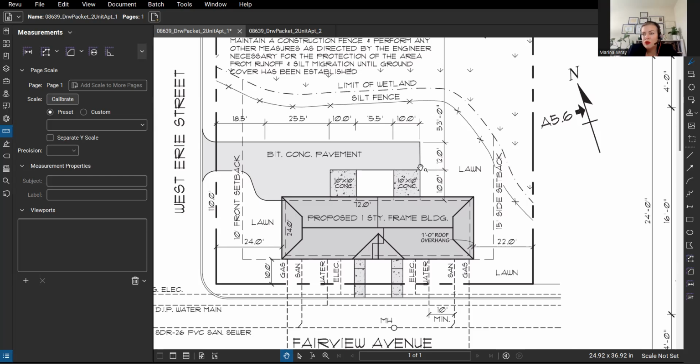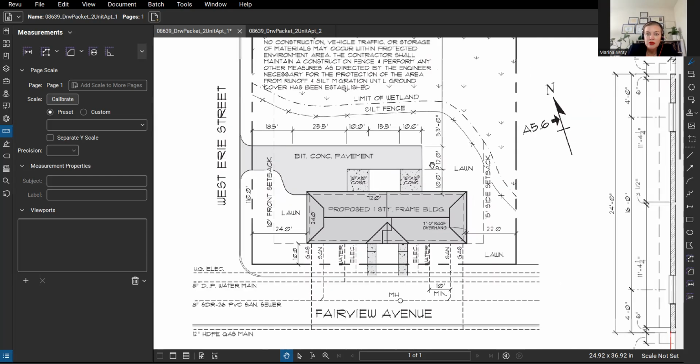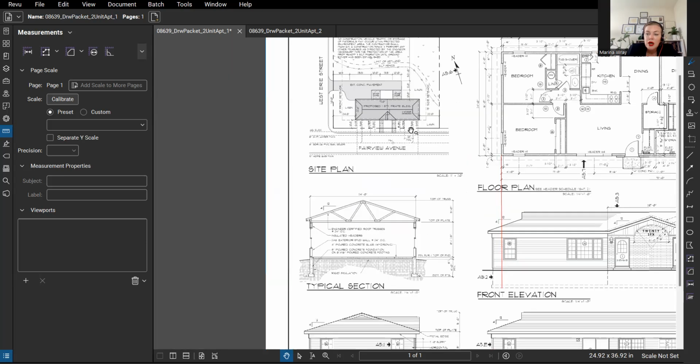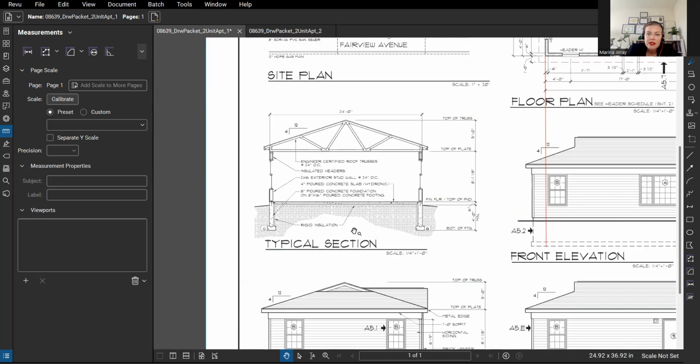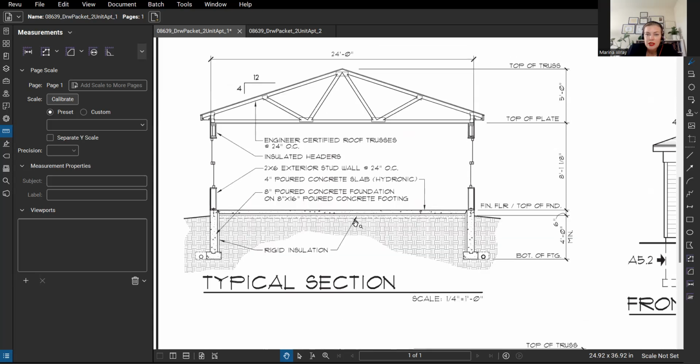And then we have to do the floor area ratio calculations. We have to do other things and check the restrictions with the local AHJ, or authority having jurisdiction. So there are other things that we need to actually review before placing the building onto the site. So let's take a look at the section as well. It is placed here.